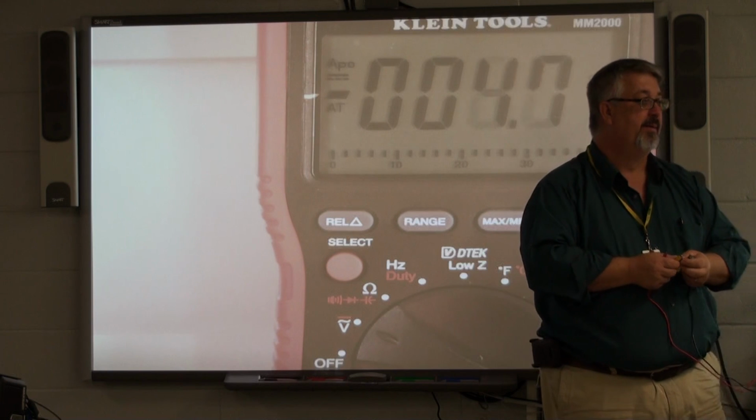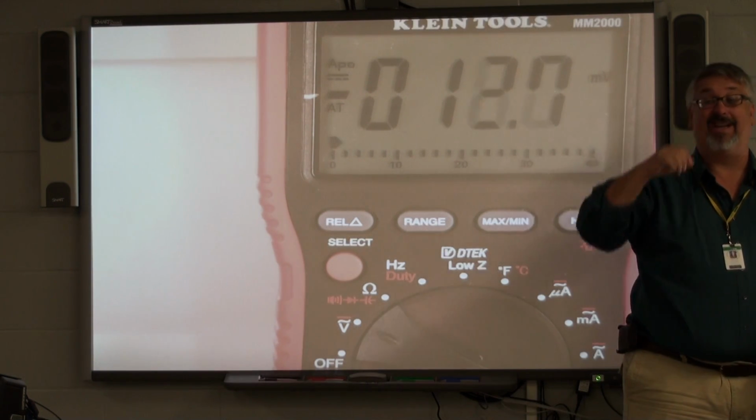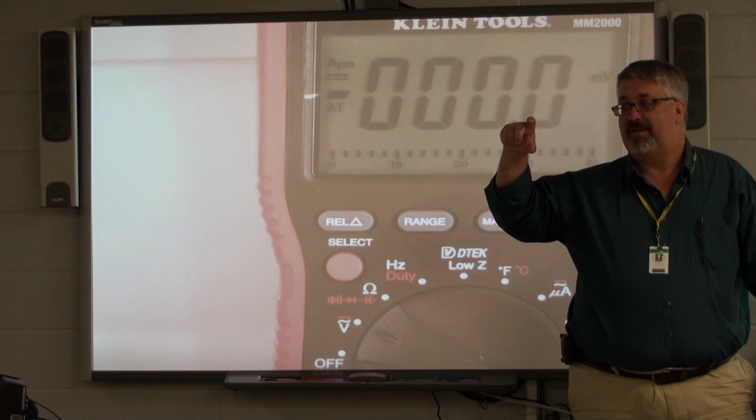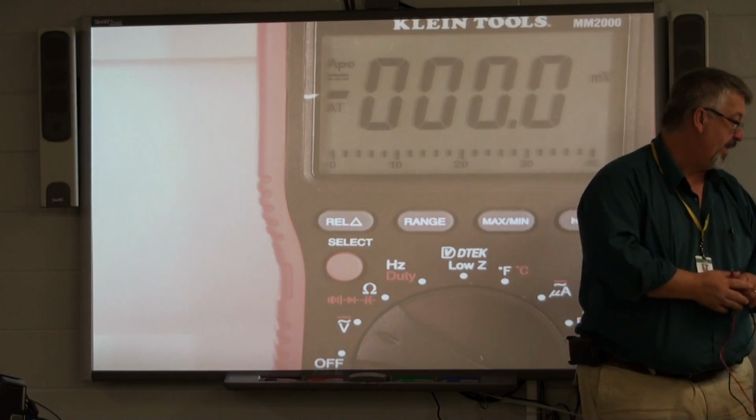It's just capacity there. I actually had a little tripod light one time that was LED, and it operated off of 3 volts. And it used 2 AA's, but it had 3 legs. I could put 2 AA's in leg A, 2 AA's in leg B, and 2 AA's in leg C. And what was happening was each one of those legs was in parallel with one another. So that just upped my capacity. It would run off one leg's worth of batteries, but if I went ahead and loaded the other 2, it just helped my capacity last a little bit.